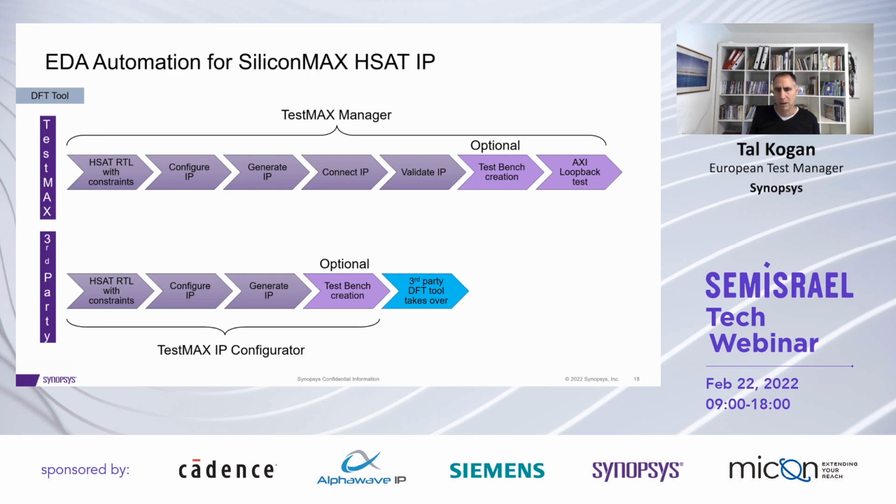But in this second approach, the generation of the scan data, whether it is, for example, STIL format or any other format that is generated, the third-party DFT tool is responsible for that. And we do support that.